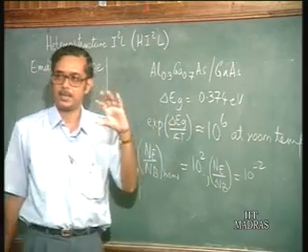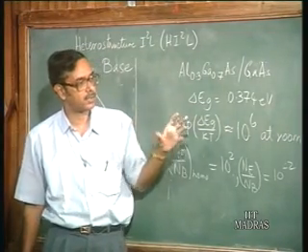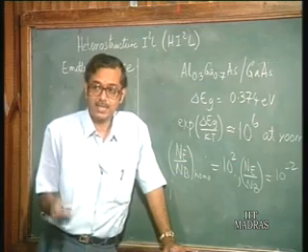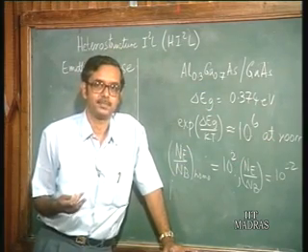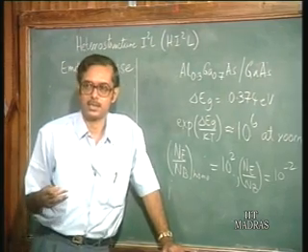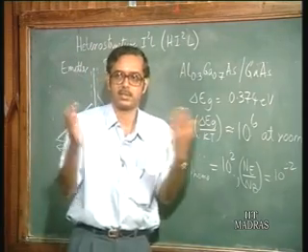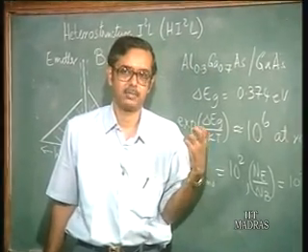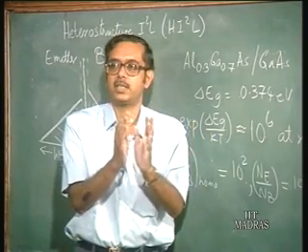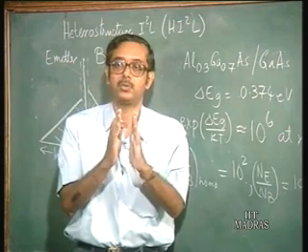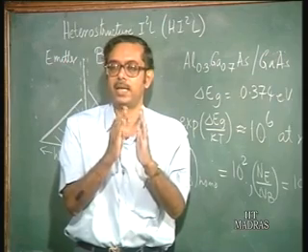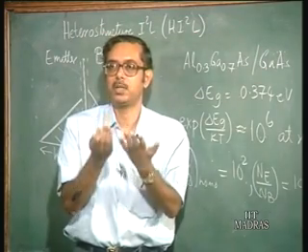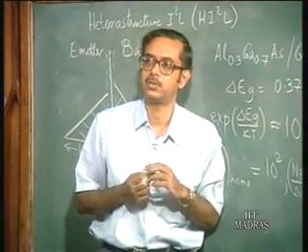So, in a heterojunction bipolar transistor, because of the large gain achieved due to the difference in band gap, usually the base doping concentration is made much larger than the emitter doping concentration. That is quite normal. It has a lot of advantages; I need not go into all that because it would take a lot of time. Some you can think of for yourself. The base resistance is reduced, which is very important in high speed transistors. Because you have a higher doping concentration in the base, you can go for shorter base widths and not worry about base punch through and other effects. If the doping concentration is high, the depletion width is going to be less, so you do not have base punch through. There are a lot of other advantages.